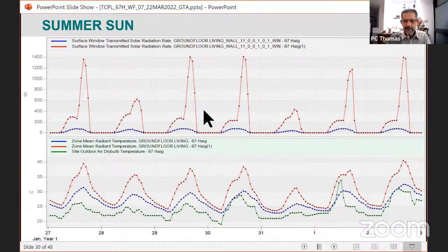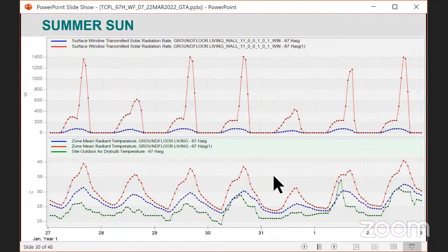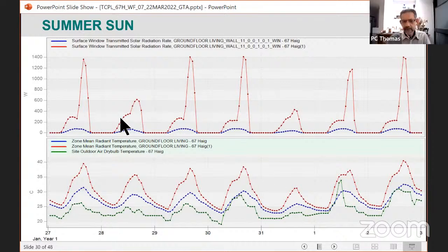Okay, so let me come back to this design. This is the south-facing window. These were those east-facing windows next to the neighbor, because I didn't want to see what was happening in the neighbor's house. These are those west-facing windows. Now those west-facing windows have got openable areas. You can open 2/3 of those windows, and that becomes useful when we look at natural ventilation.